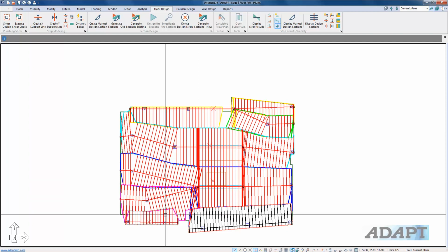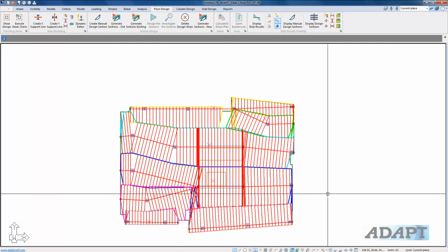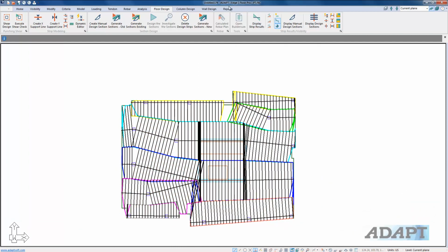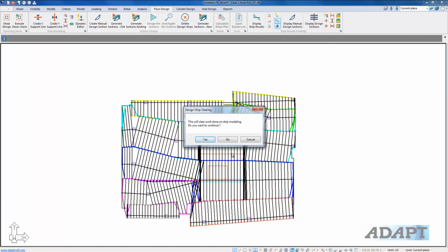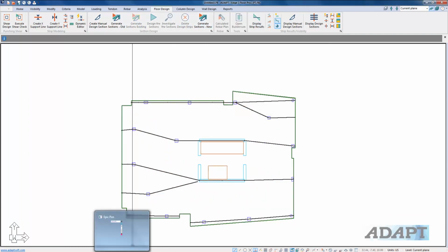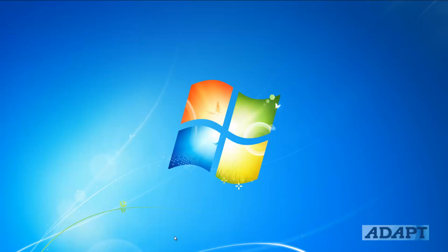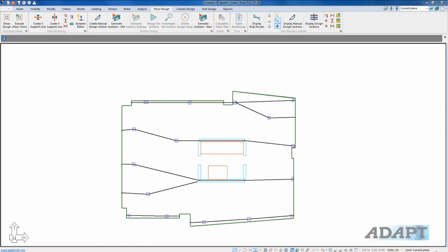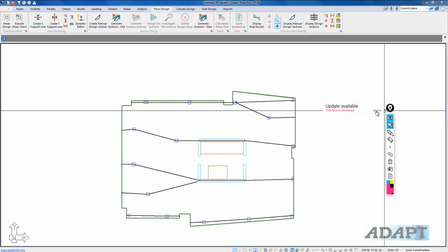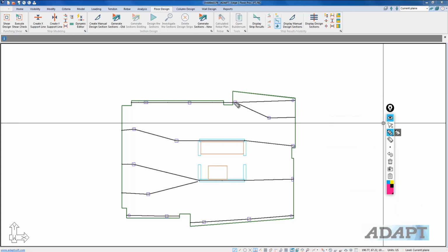So this generates the strips without any input of splitters, based on the options that we just selected for input of our support lines. Now, had we done that in the previous version, we would have had to add splitters at several points, just as a matter of comparison. Let me show this. I'm going to add a little tool here. We would have had to have an X direction splitter here, and an X direction splitter there. And so that's two splitters in this direction.